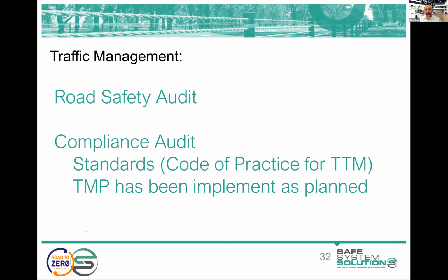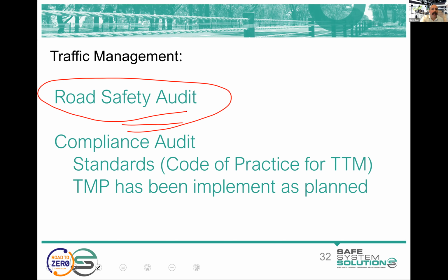Now, it is available as an option in New Zealand. And one of the key challenges that I see with this is the confusion on the terminology. And so I put this one up straight away off the bat. We've got this idea that you could road safety audit a traffic management construction site. But then there's this sort of compliance auditing. Now, the compliance auditing is the checking whether it meets the code of practice for temporary traffic management, any relevant standards and the like.